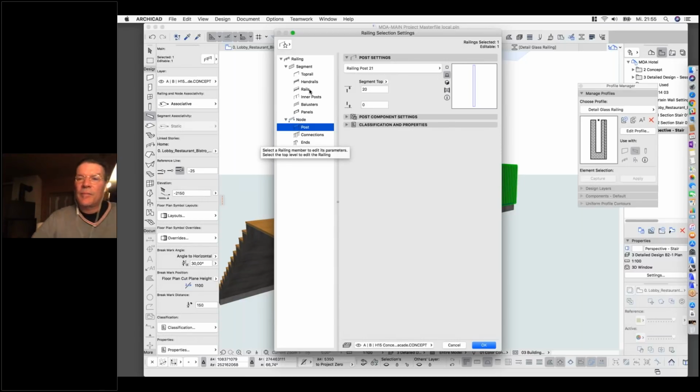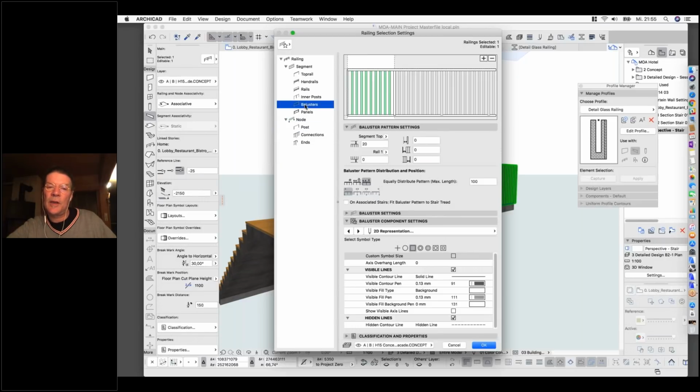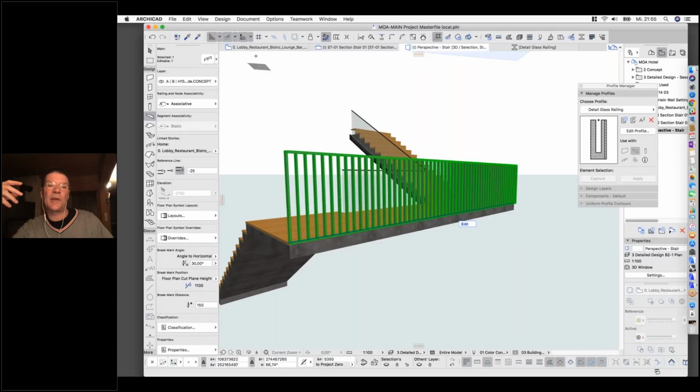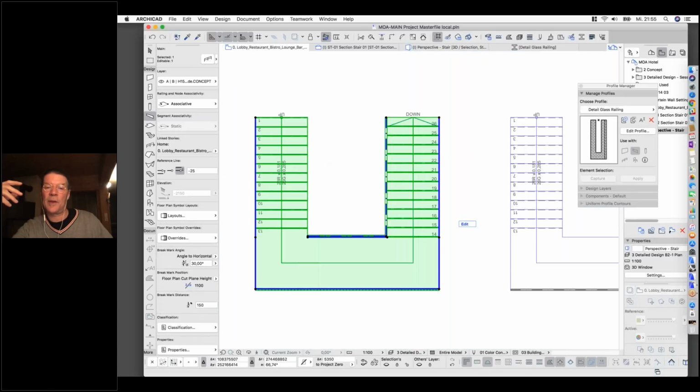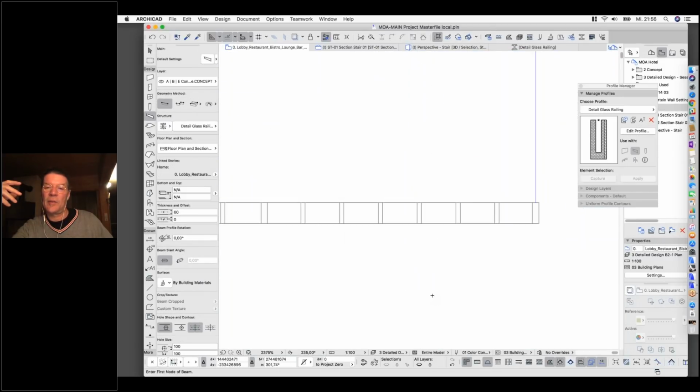It is ridiculous, but it's the 2D representation, and you can find it down here. The 2D representation somehow is not projected, but you can choose the form, and by default it's set to a circle. So that's a bit confusing. If you just make a quick setup, you will end up with a 2D representation on the floor plan which does not fit. In this case, it works, because as you see, it's rectangular.